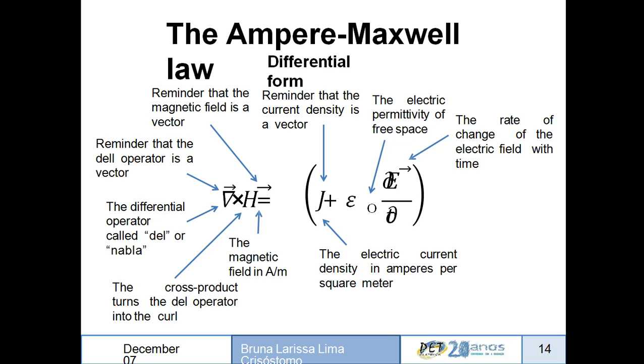Suppose there are 20 or 40 positive poles, then in very close proximity there will be the same amount of negative poles in that enclosed surface. So the surface integral of the dot product of the magnetic flux density and the infinitesimal small area, B dot dA, gives a zero value, as written in the integral form.